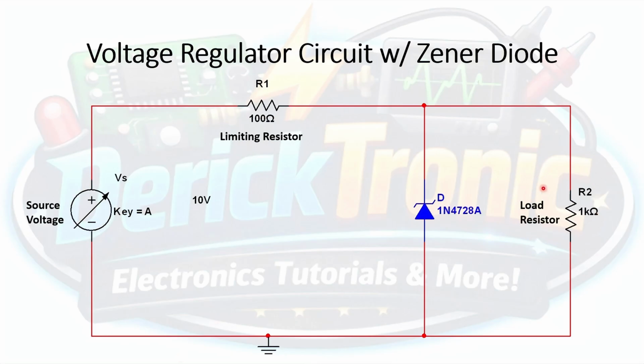R2. We could take a look at this load resistor as something like an equipment or a device that you plug at the end of a circuit. So that can be anything. That can be a refrigerator, a television, a laptop, a tablet, or whatever. Now, the Zener diode, as you see here, will be connected in parallel with our load. Another interesting thing that you might want to notice here is that the Zener diode is in reverse bias.